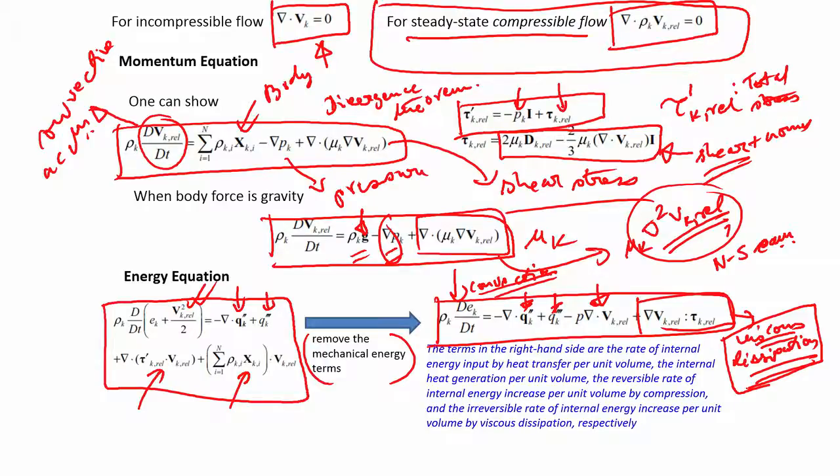But when I spread the fingers out, the shear stress is very low. So, viscous dissipation is important, especially if you have a very high velocity flow going through a constrained space. It is a function of the shear stress, and the shear stress is basically the derivative of the velocity. So, how do you write it? It is like a typical component.